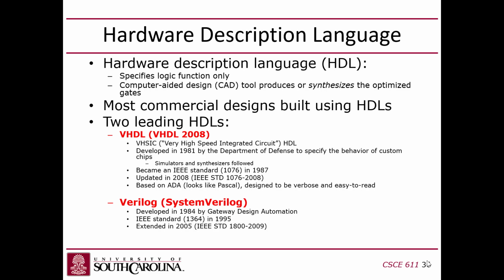Just on that note, I was going to ask if there are any downsides to using SystemVerilog over Verilog. The only downside, and the reason I resisted switching for years, is that a lot of legacy code is written in Verilog. I was teaching Verilog because if you go out and get a job and have to look at code written in Verilog, it would be good for you to understand its idiosyncrasies. But the textbook switched from Verilog to SystemVerilog, and I got sick of dealing with some of the problems, and I'll mention what some of those are specifically as we go through. But not really, they're very similar. And if you know one, you can always learn the other one pretty easily.